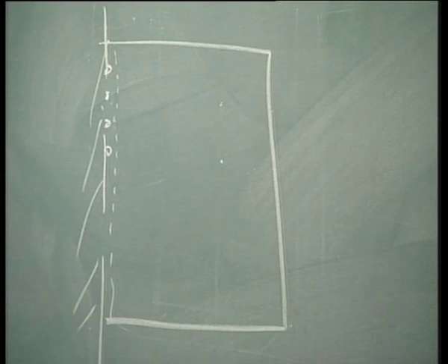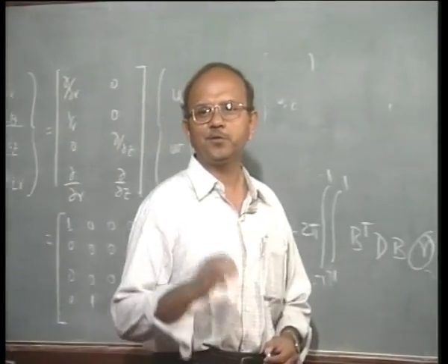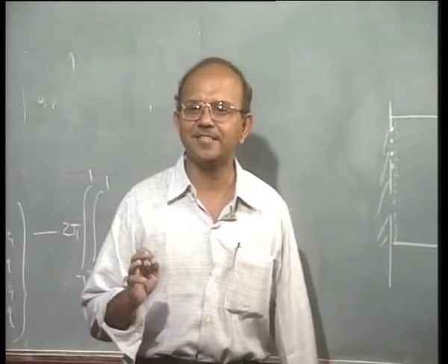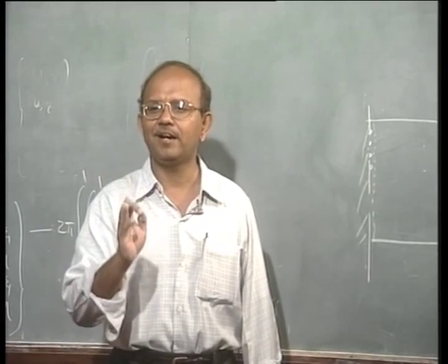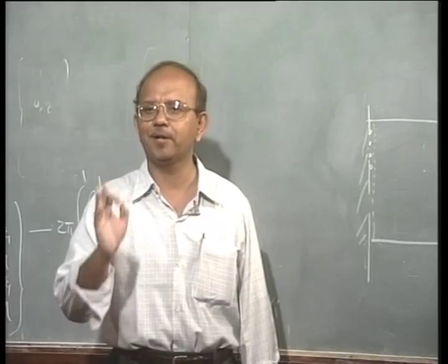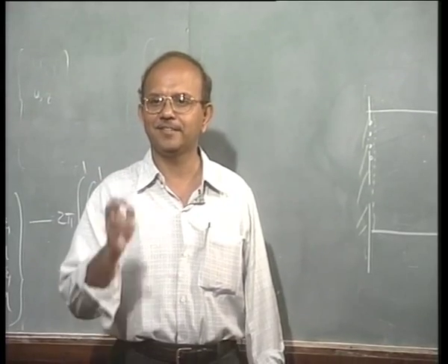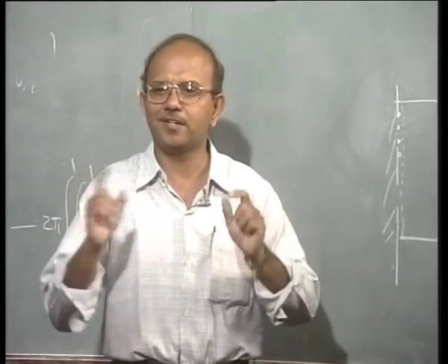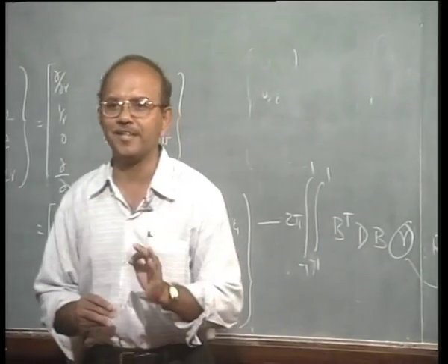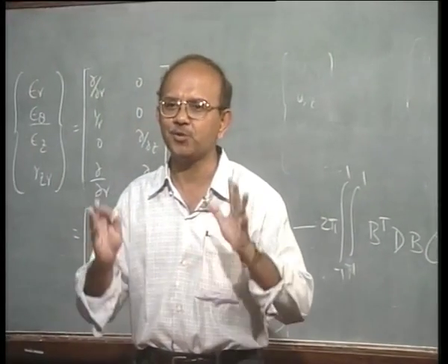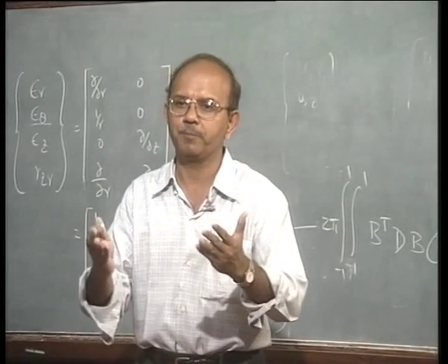Is this clear? So yeah. In that case, we are going to actually have a failure at the center. Please note that failures are not shown as a hole in finite element analysis. This I told the boss, within quotes, who does not understand what is happening. Okay. The problem is that the failure has to be interpreted by you.